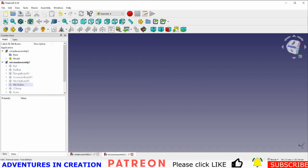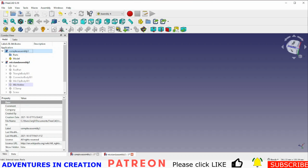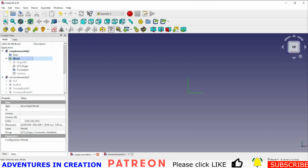Okay, I've gone through all the parts. I've added LCSs to all the parts. Now we're going to assemble them into our model. So I'm going to go back into this sheet and make that the current sheet. And then what I want to do is assemble parts into my model. So I'm going to make the model current.